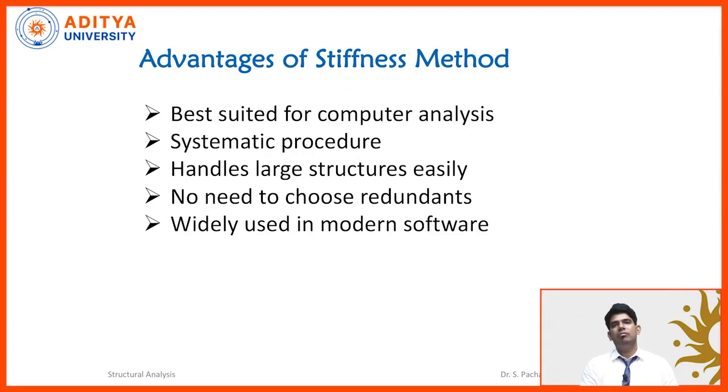Now, what are the various advantages of the stiffness matrix method? It is best suited for computer analysis because we need not worry about the choice of redundant forces, because the stiffness matrix method depends on the number of unknown displacements. We have a systematic procedure, it's not complex like the flexibility matrix method, and it handles large structures easily. That is why in STAAD.Pro or ETABS, the stiffness matrix method is the solver, not the flexibility matrix method.